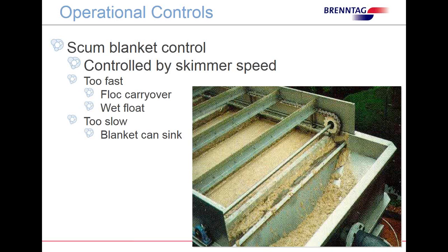Some additional operational controls we need to consider: scum blanket control. We're controlling the skimmer speed. If it's too fast, we can get carryover. We can also get wet float. If it's too slow, the blanket can sink on us.